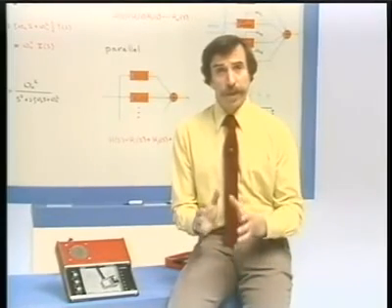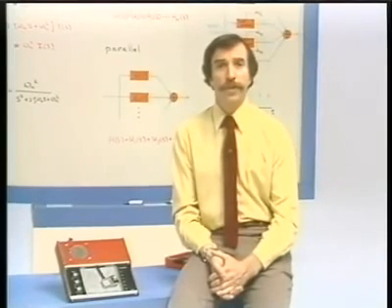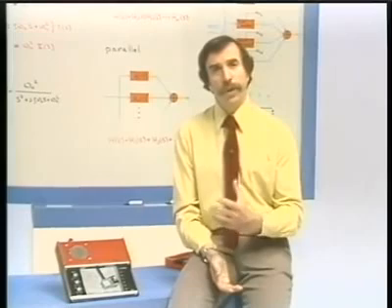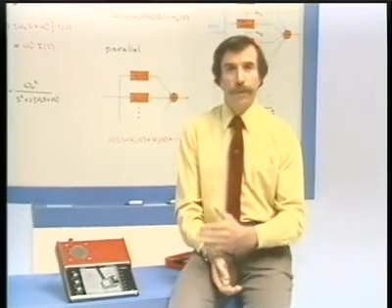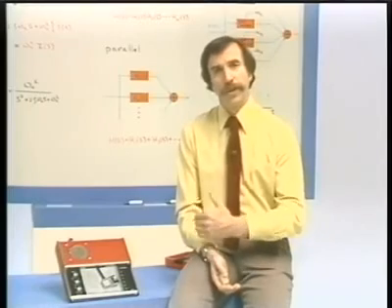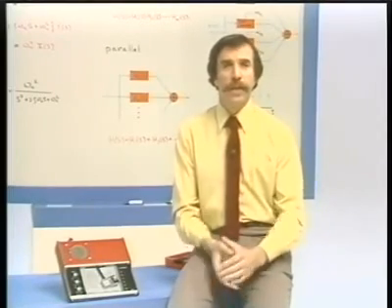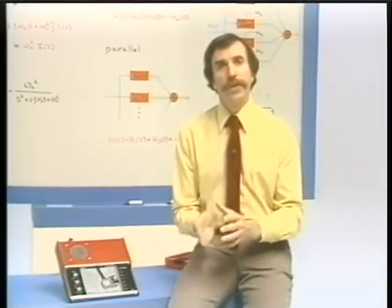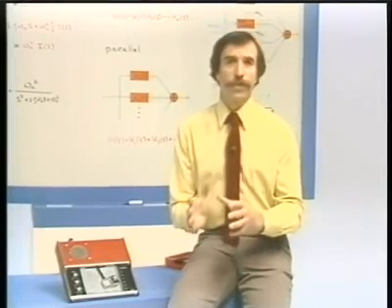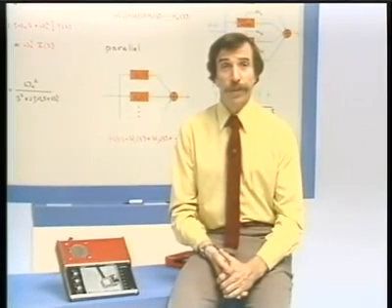In the next lecture, what I'd like to do is parallel the discussion for discrete time, turn our attention to the Z-transform, and as you can imagine, simply by virtue of the fact that I've kind of shown you a digital and analog version of very much the same kind of system, the discussions parallel themselves very strongly, and the Z-transform will play very much the same role in discrete time that the Laplace transform does in continuous time.